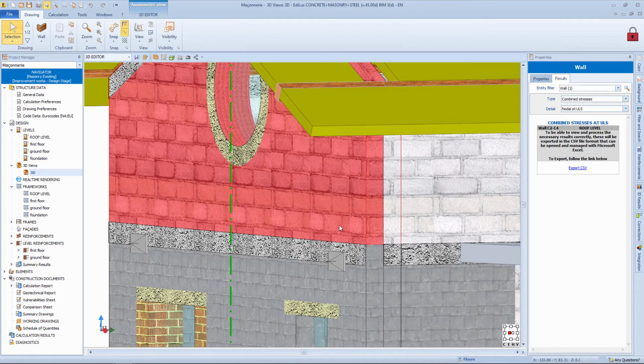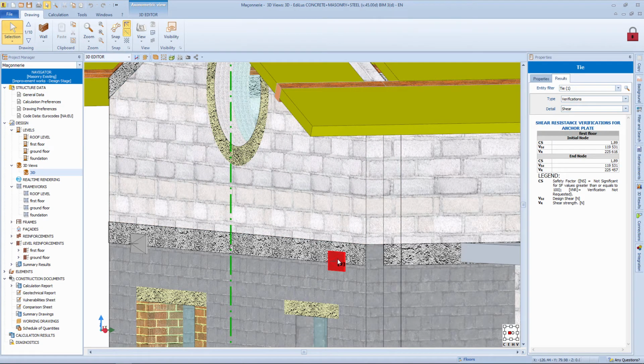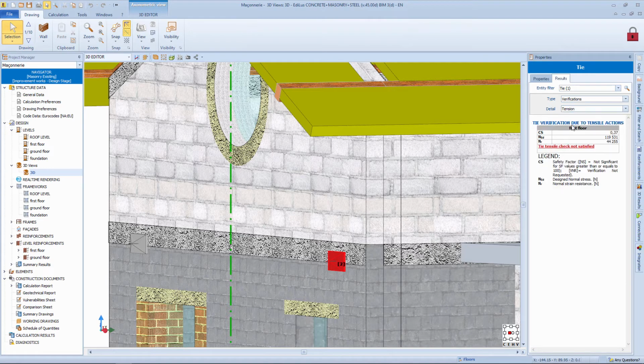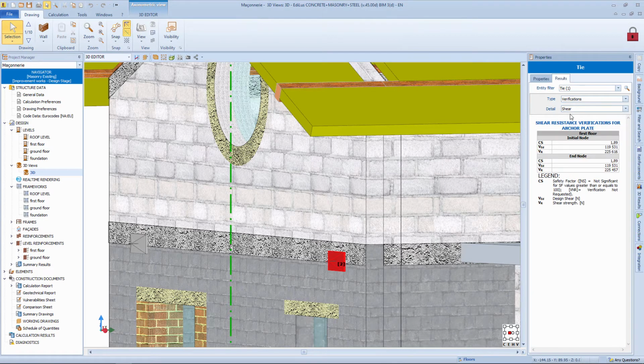When we add the chains to the model, we obviously have to run the punching, shear and traction verification with the wall. The calculation of these parameters depends on where and how the chain was positioned. In this case, the chain was positioned in a reinforced concrete edge beam. Consequently, the shear and punching resistance takes into account the characteristics of the concrete, and therefore we see a greater contribution than for a chain positioned on the wall.